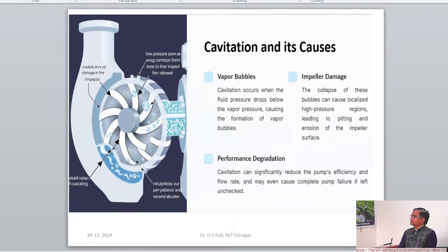The pump will always lose some power when it converts and transmits this electrical energy into mechanical energy. And this will be lost through the couplings, the bearings, the shaft, the seals, the cooling fan, etc. For example, on this chart, we can see that if the pump provided 125 gallons per minute at 25 feet of head, then it would run at around 67% efficiency, which isn't very good. If the same pump operated at 30 feet of head for 138 gallons per minute, then it would operate at its peak performance.